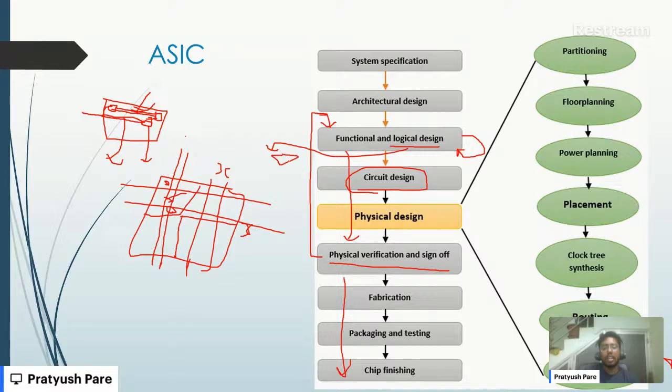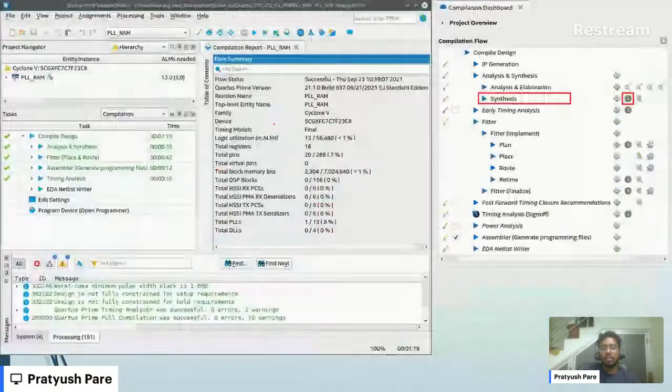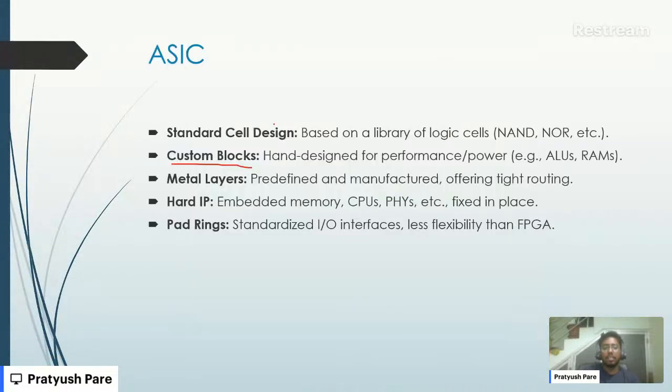In addition to that, the building blocks of our ASIC, these standard cell designs, are also done by analog engineers. A NAND gate is not what we digital engineers draw. It's not exactly that. It's made of PMOS and NMOS, so this is designed by an analog design engineer.